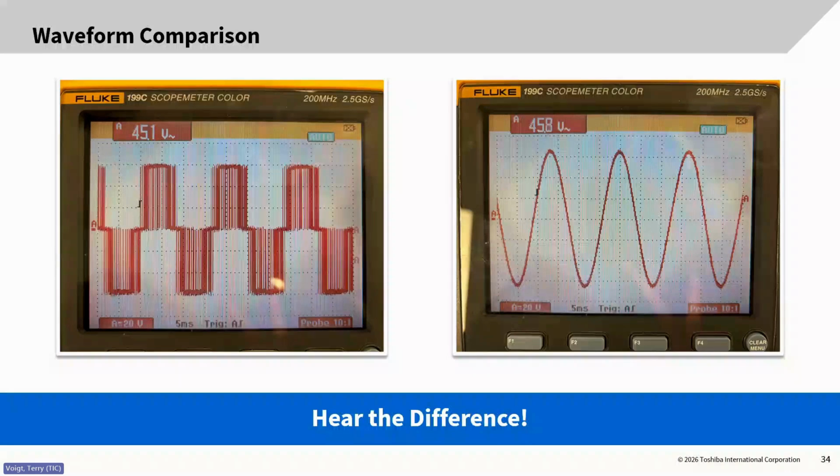The carrier frequency is the frequency that the drive uses to create that PWM waveform, and that's what we're hearing. But in the case of the WC1, that's the waveform on the right side, and that's the output voltage, the voltage going to the motor from the WC1. So they're very, very different waveforms. When you hear this drive run, the first thing you notice is you can't tell that the motor's running. You can hear the water running, you can hear the bearings spin, but normally you would hear the voltage inside the motor. With the WC1, you can't hear that. It is quite incredible.